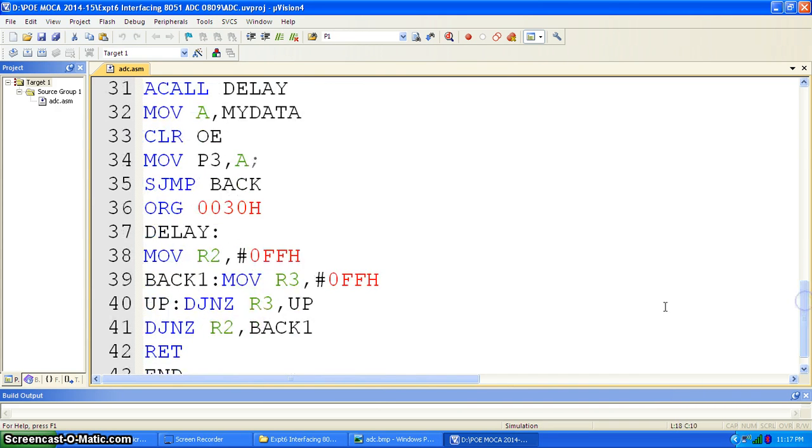Okay, fine. Everywhere you are using delay, whenever you are sending some pulse you want to have some delay in between two values. So for that, this is a small delay program. In this software delay, you write some value in some register and go on decrementing that. So these two registers are used and that value is decremented to get this particular delay.